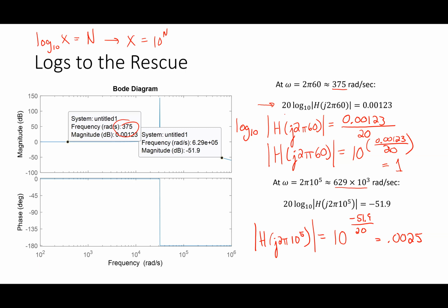So basically, you're shortening the amplitude, right? Yeah, I'm reducing the amplitude at those frequencies. And it's hard to see that reduction if I look at a linear scale, so we look at a logarithmic scale instead. This doesn't mean that the amplitude of that signal is 1. This is just a transfer function which you would multiply by.